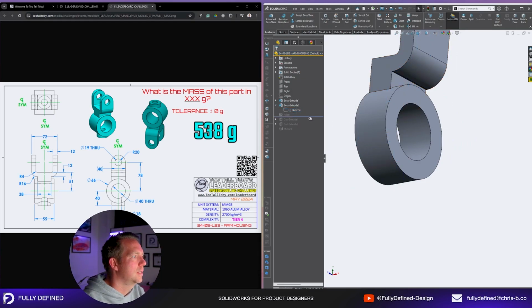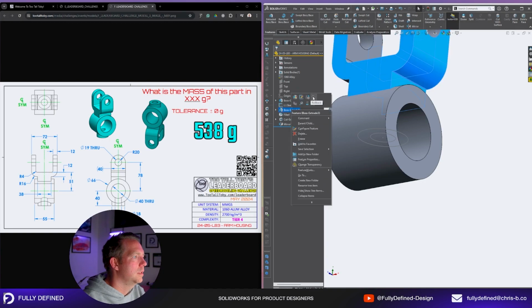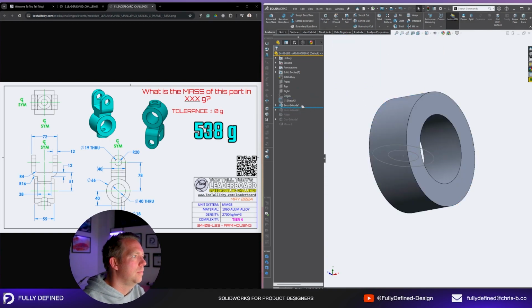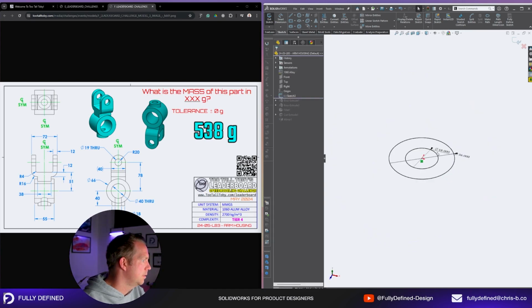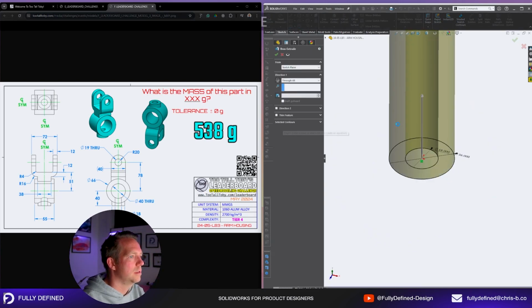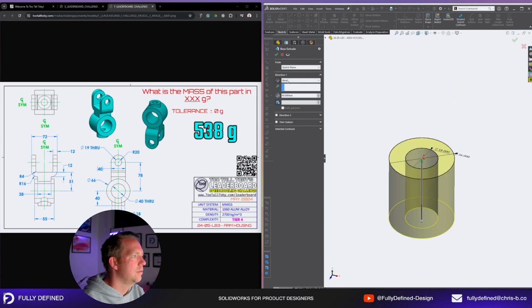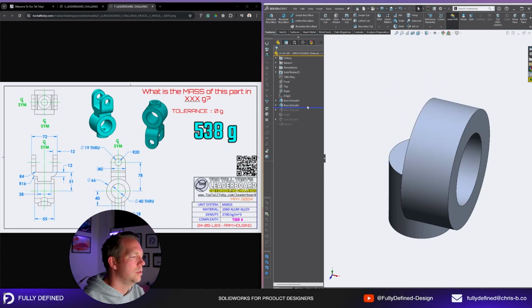Is that why it didn't want to work? Because of that cut extrude, I bet. So delete the cut extrude. You can bring it below. You can do this sketch first, rejoin it to the origin, and that goes down 40. So it's just going to be up, down? I'm going down 40, because then the next sketch can still be on the origin.